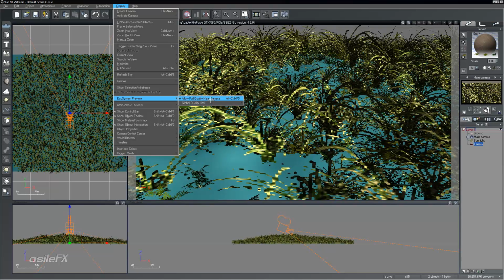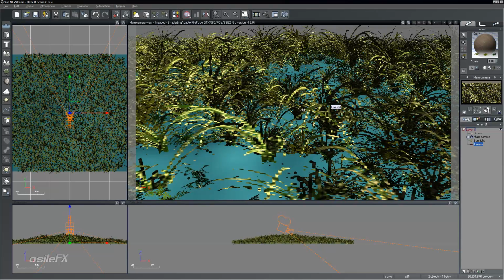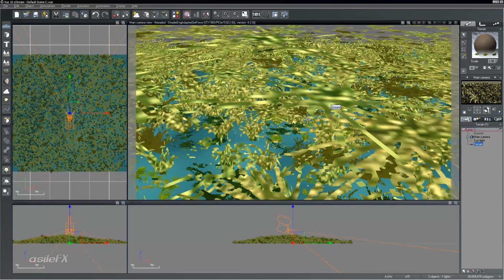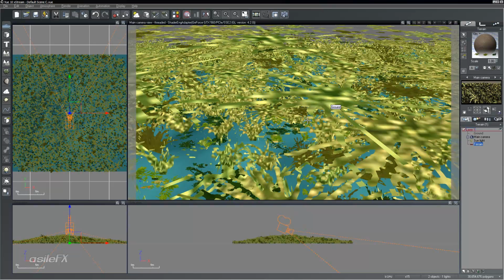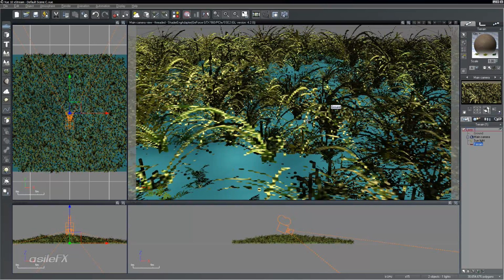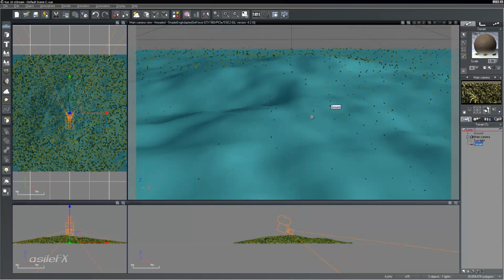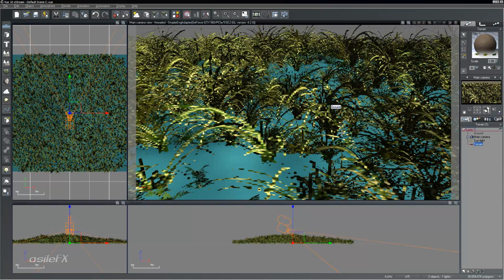So what I have done is gone ahead and created keyboard shortcuts for this that I use quite frequently in order to be able to just switch between different display modes. I can go to the billboard mode, or I can switch to the shaded billboard. I can turn off EcoSystem display, which will just show dots. And then I can also enable or disable the full quality near camera.